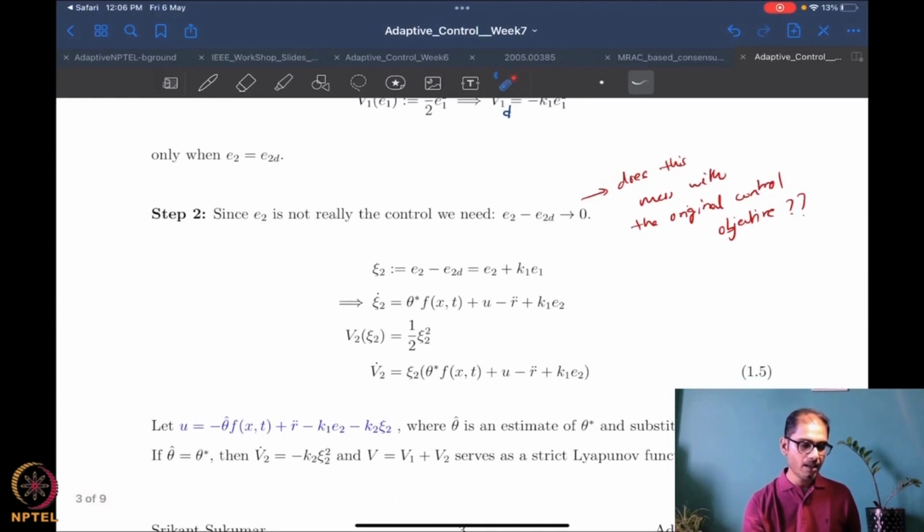Okay, great. And now what do I do? Construct the dynamics for this error. The steps are similar. Compute an error that you want to drive to 0. Compute the dynamics of the error. Then start to do Lyapunov analysis on that. So the steps are standard, and there should be no confusion as to what direction you need to take when you start with a problem. Always try to construct an error, then design a Lyapunov candidate, then define a control, then find an update law. Same steps.